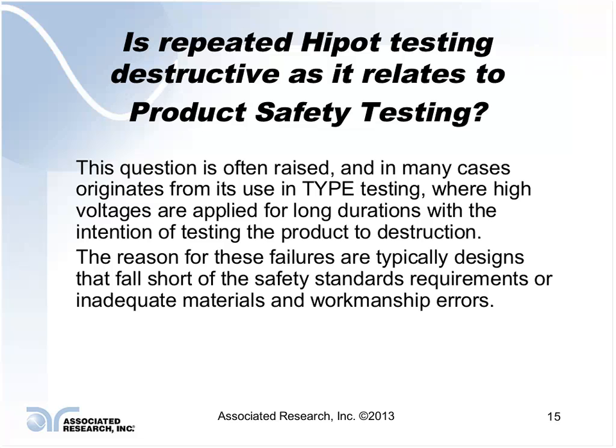Now, when the product comes into my facility and I'm getting ready to use them in my product, I may go through and test them. We've done it as part of an incoming inspection where we've done Hipot tests, especially where we've changed suppliers and we're trying to evaluate the product itself.